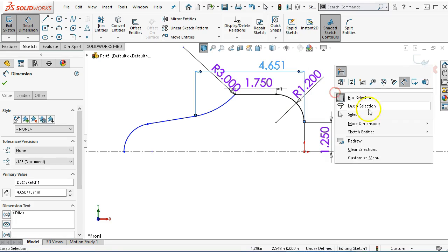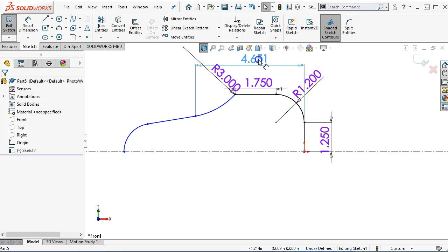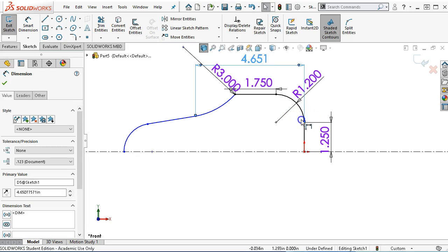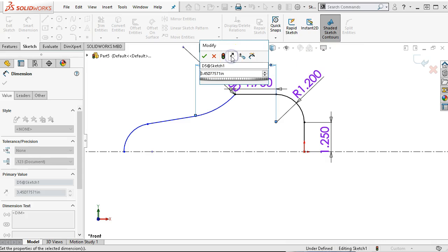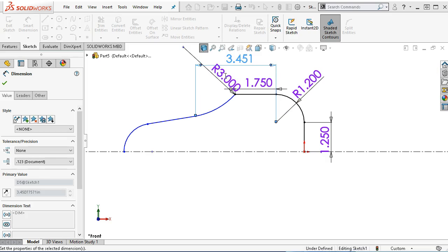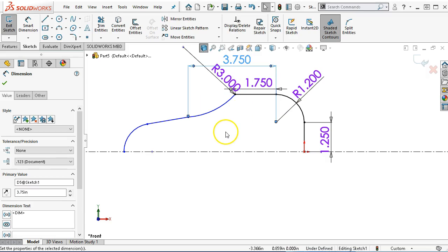Yep. So here's that decision time again of, do I drag from the handle and reposition it? Oh, that was interesting. So accidentally hit the reverse the sense. That put it in a negative value, sent it the opposite way. So just watch out for those buttons.